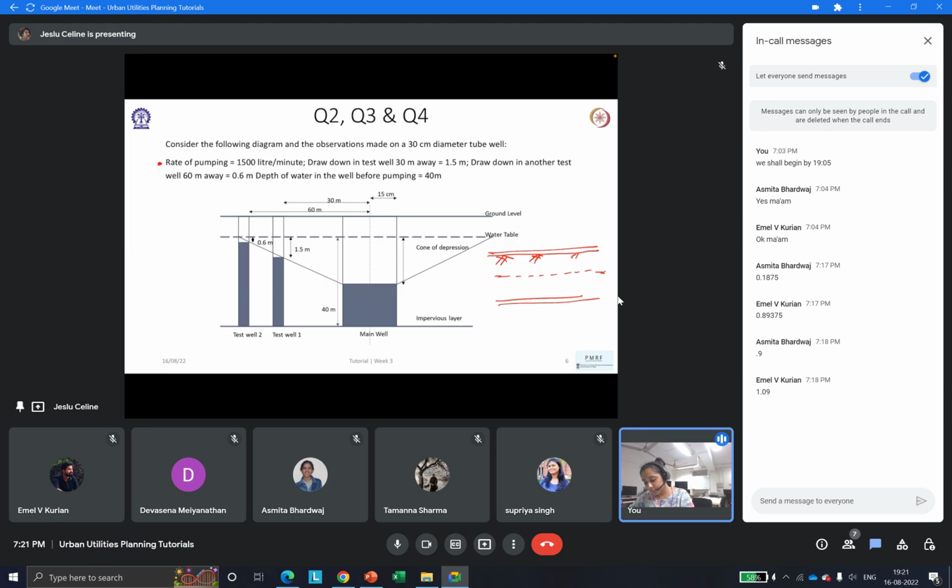So once we dig a well and start drawing water from a well, or any source that takes water out, water will start rushing in, like we are taking water in from them. So now this creates a depression. This depression is also known as the cone of depression.